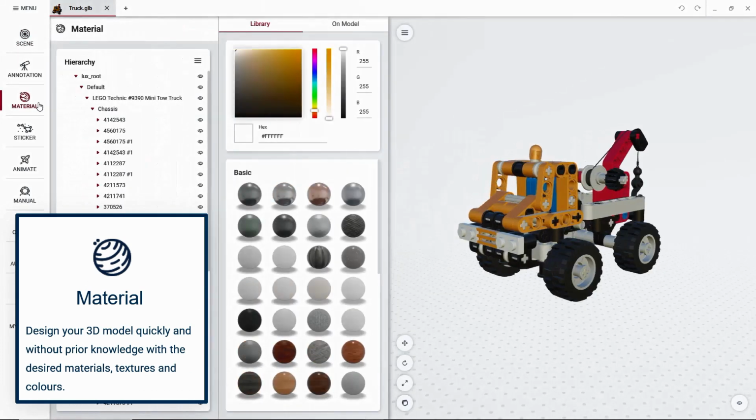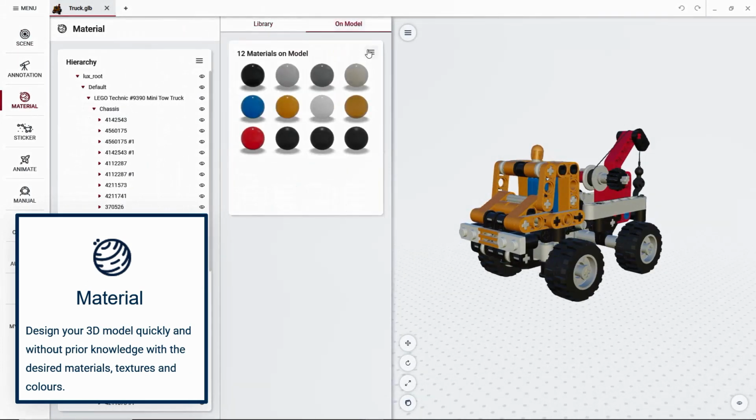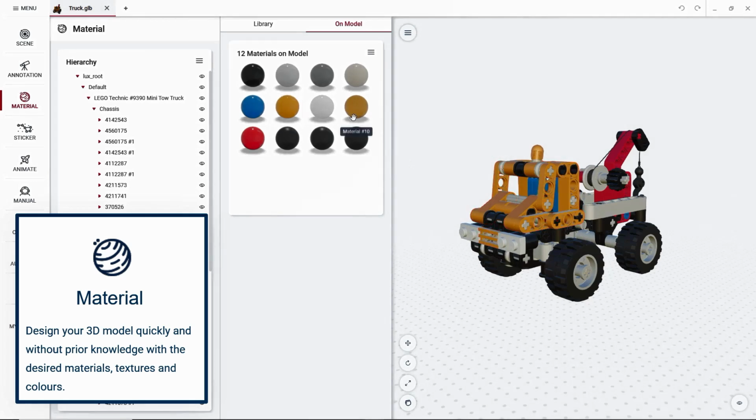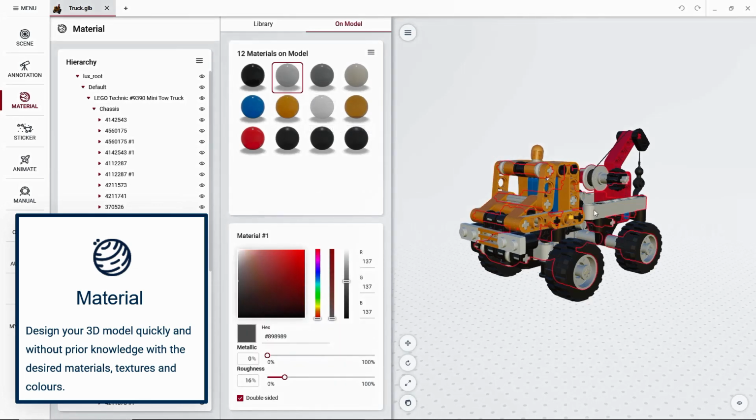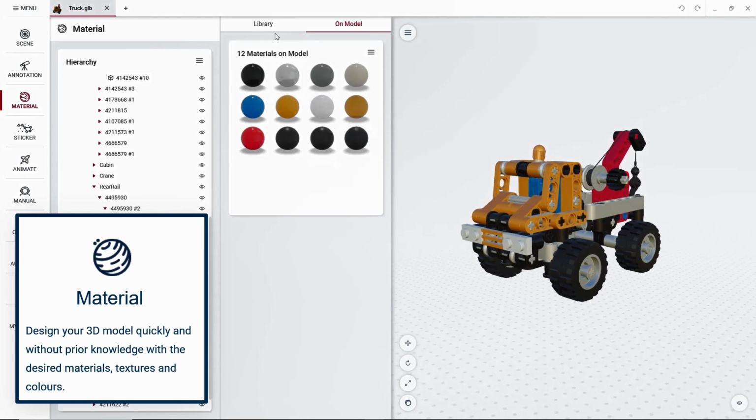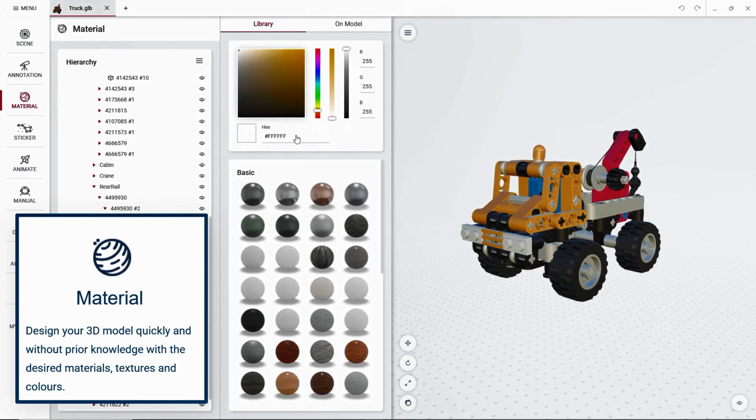Once you've brought your model in, you can then tweak materials. If you have used a file from KeyShot itself, it will show you what those materials are. As it is a different file format compared to what you'll see when you do your final renders out of KeyShot, NeoSpace allows you to tweak those materials in any way. If they've come in with not enough roughness or not enough metallic elements, you can use the sliders to add or decrease those values. And you can also manipulate the colouring if need be.